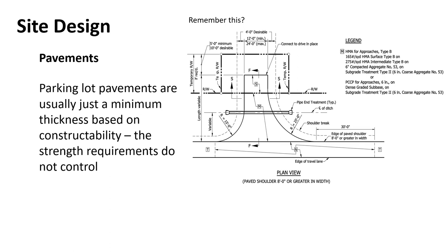What it turns out to be is that contractors are really bad at it. When we get down to 1 inch, their paver is just not accurate enough to keep that inch depth. And you're going to have shallow spots, you're going to have deep spots. It's just not going to be great. We used to try it. It didn't work. All right, so 1.5 inches is your minimum pavement depth for a surface mix, and that's just what it is, right?